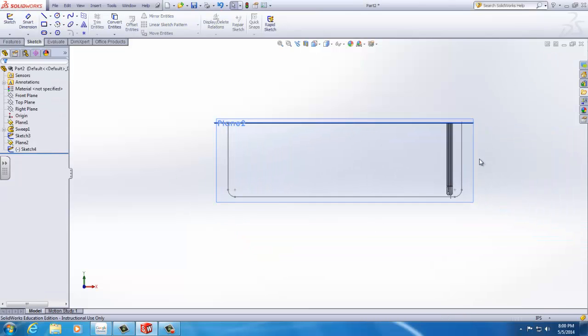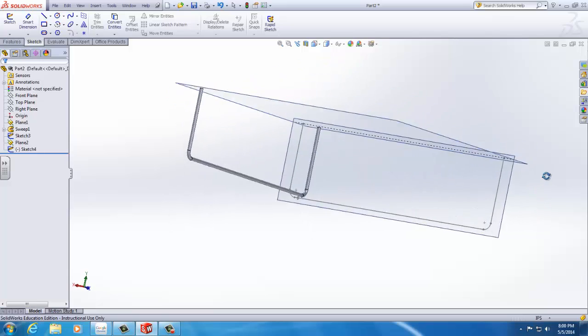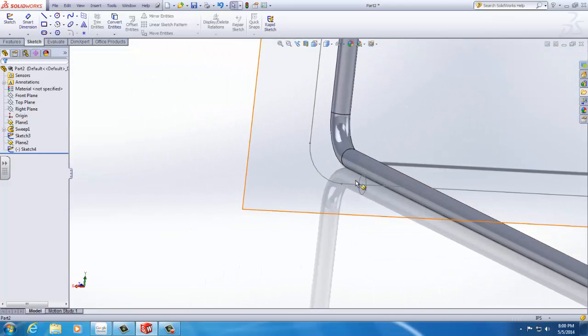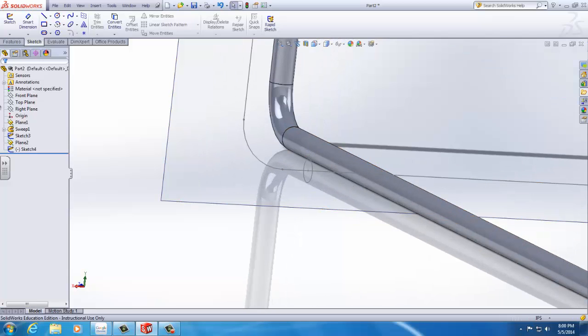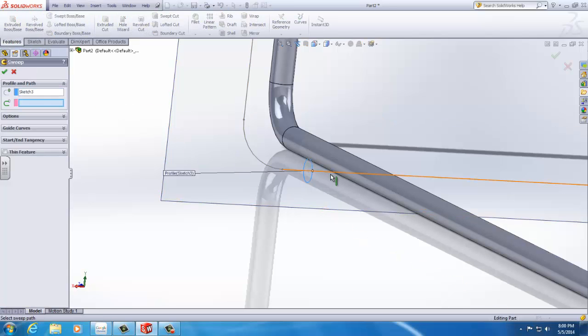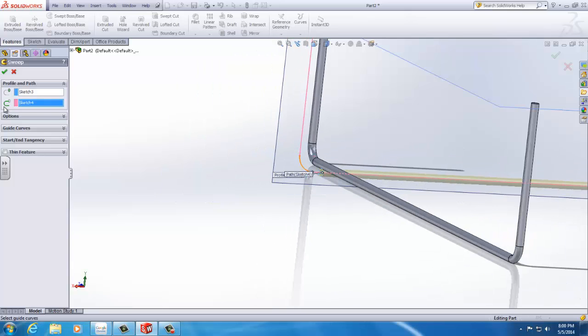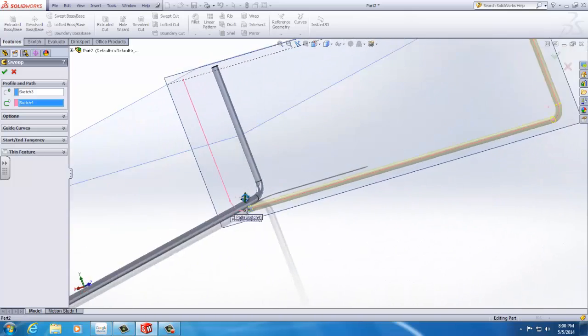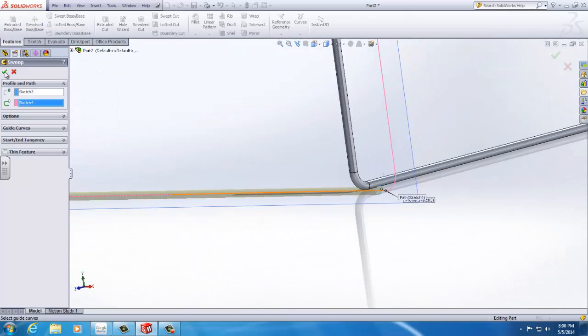And we're going to do the move command, start point, and we're going to do the sweep again. This time we have to do the sweep twice because I have the lines on both sides. Keep an eye on that issue. I go back to my second sketch. Select that point to take the origin, and we go with the path, coincident, which is the bad part about sweeping: it doesn't give you the option of going both ways. So we have to do it twice, and play around to make sure it's the shape I'm looking for.